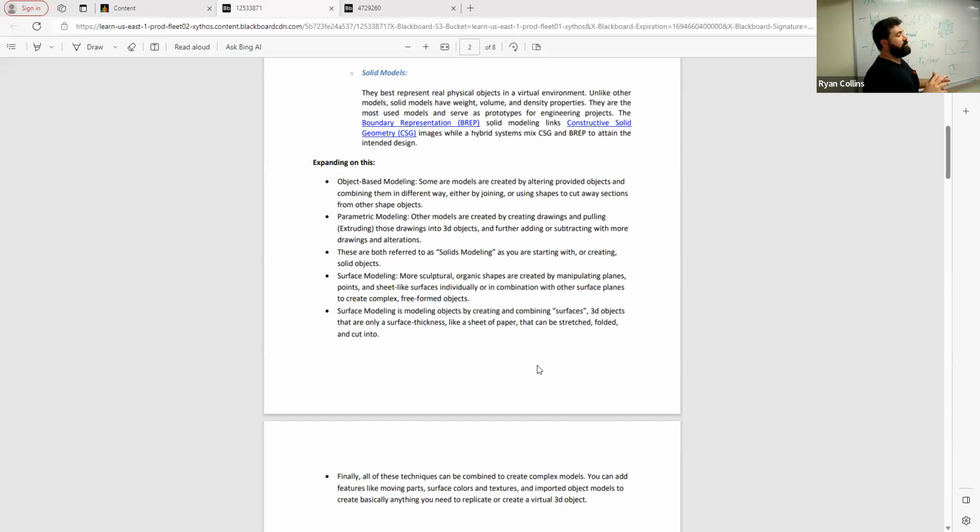It just distorts and reshapes with the properties that you have restated. Meaning, maybe I made all of this slope, but you know what? Later on, I decided, oh, actually, this thing needs to be, instead of 5 millimeters, it should have been 10 millimeters long. You'll still have this side profile information, but instead of it only being 5 millimeters, you can go back, redefine that.